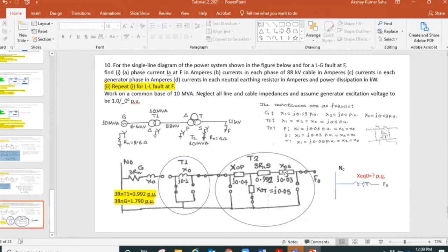I can see impedance, but I still can go. It's opposing, it's impeding, but I still can go through if I have enough force. Come to this one. Yes, there is closing here because of the delta connection of the tertiary winding. I can go through, and this way straight, no impedance. So this is one line that you must draw, just like this, horizontal, this reactance horizontal, this reactance in vertical combination. If you don't understand, still just draw it like that, and then draw this horizontal line reaching the neutral bus. So that one is complete.